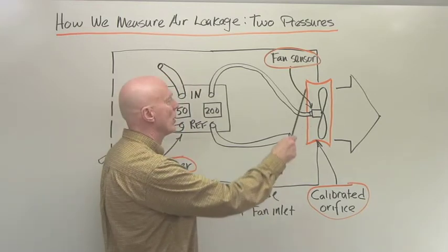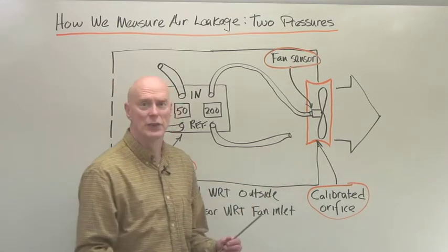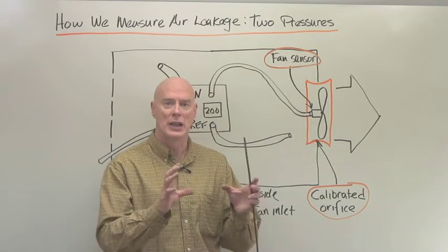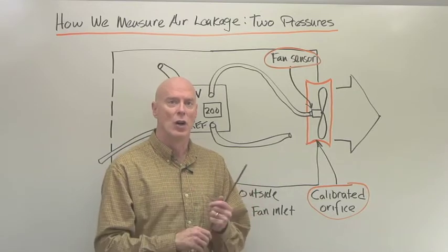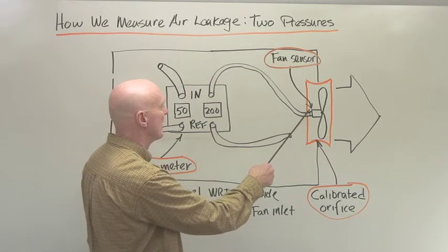Either we can have the orifice completely open, or we can have plates in here that make different sizes of orifice. But the important part to realize is it's a calibrated orifice, so that's going to help us measure. And there's also a fan sensor in there.